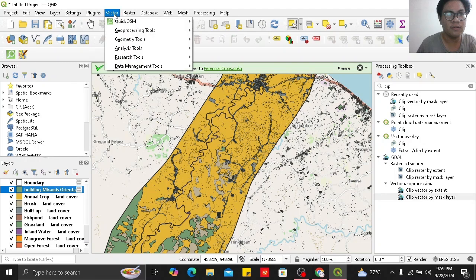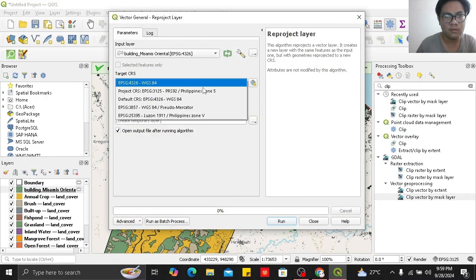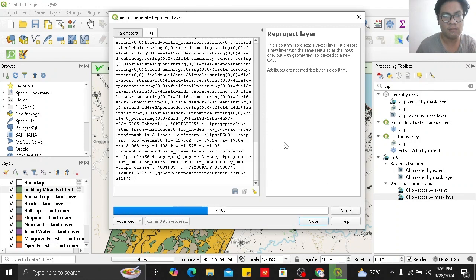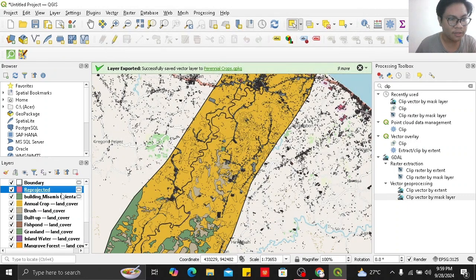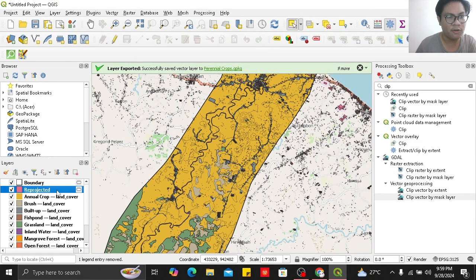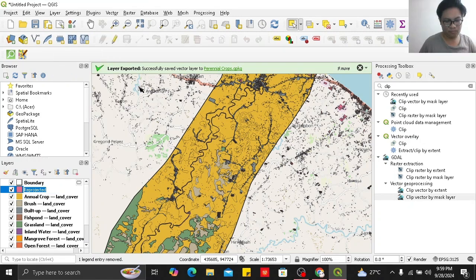that layer, so go to vector again. Same way that we did with the rest. So we click on zone 5 and run. Cool. Done. You may delete the old one and rename this as your new buildings. We actually want to merge this with the current built up.